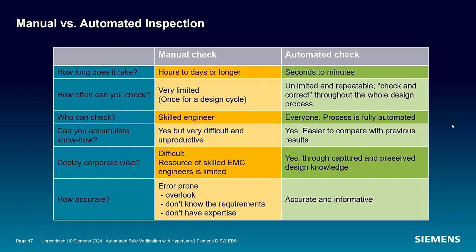But a lot of these checks don't require that deeper of a dive. Also, because the process is captured and preserved with the rules, you can deploy these rules and parameters to future versions of the board, or in the cases where you copy and paste PCB, manage blocks, and circuitry to future designs, bring the rules with you and capture the electrical verification process so that you can easily repeat it for future work.